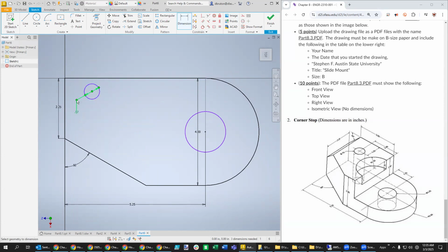3/4 of an inch. Click, click, 0.75. And then over on this one, we have a diameter of 1.25. That's fully constrained, but not this one over here. Want to place it a distance of 2 inches from this edge that we haven't drawn yet. But also we want it to be a distance of 1.25 from that edge. Let's go ahead and put that slope or that drop off, that cliff in place just by drawing it like this.